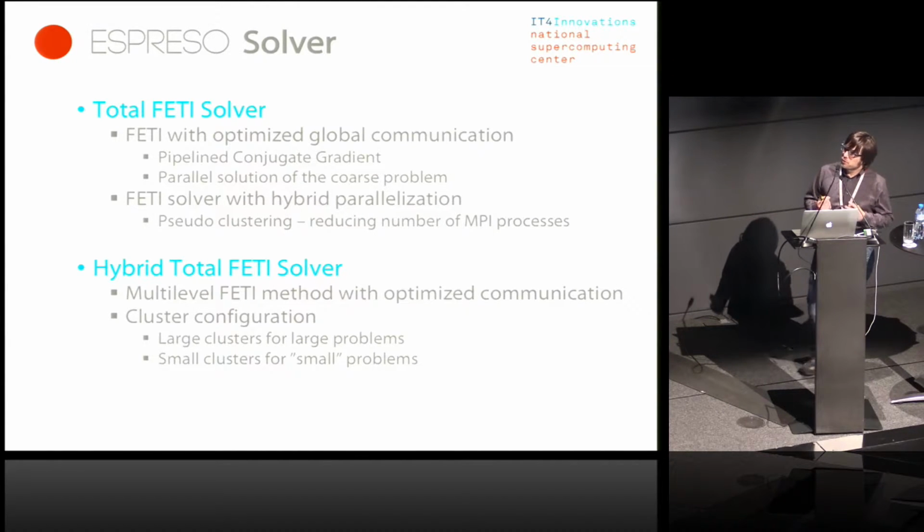You are not forced to use large subdomains. Then the hybrid FETI solver takes the best out of all the techniques that we developed for the FETI, which is all the global communication optimization, all the communications, plus the processing of the Coarse problem. It takes the best out of it and then adds the ingredient that reduces the Coarse problem size.